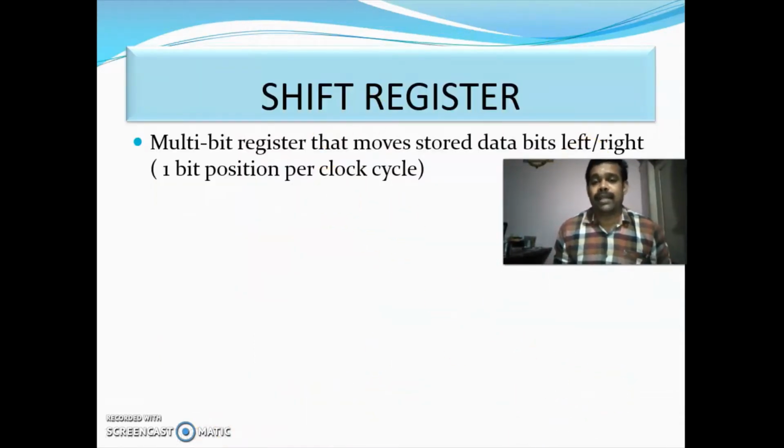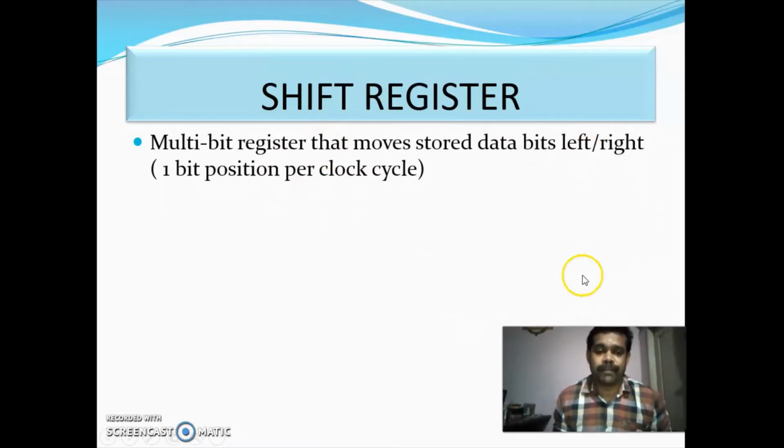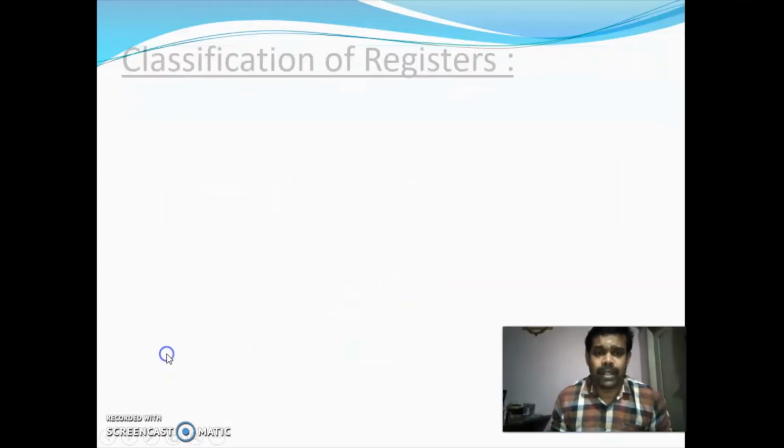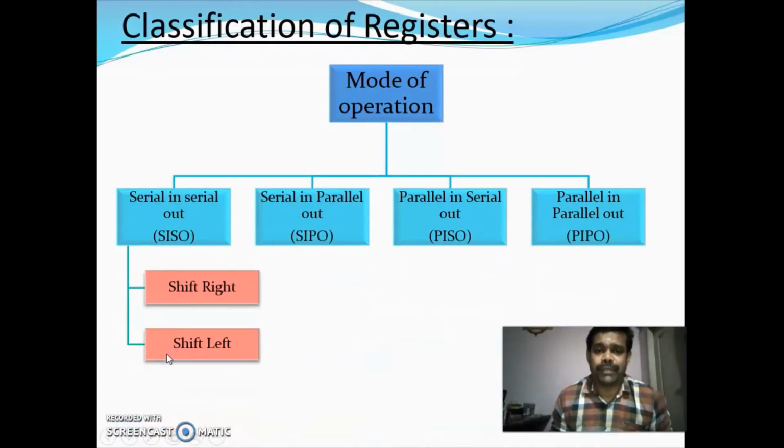So next we are going to study shift register. Shift register is a multi-bit register. It will have more than one flip-flop, and its function is to move the bits right or left depending upon the clock. Depending upon the clock pulse, it will either shift right or left.